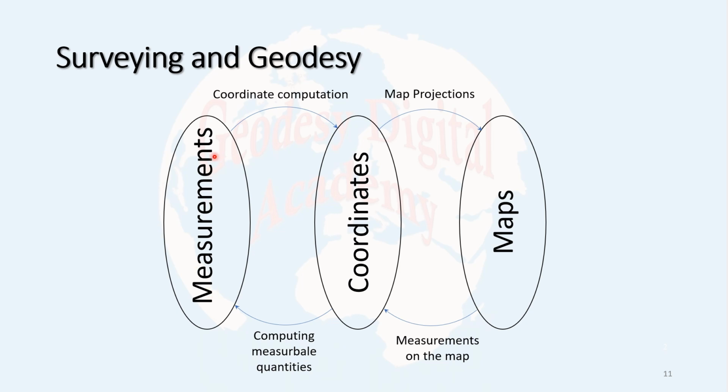But in geodesy, when the size of the area is larger, you cannot ignore the curvature of the Earth. Even if you do measurements based on planar geometry, for example measuring distances, angles, heights, whatever, for computations, preparing them for the coordinates, you have to compute how much these measurements will be at the surface of the ellipsoid.